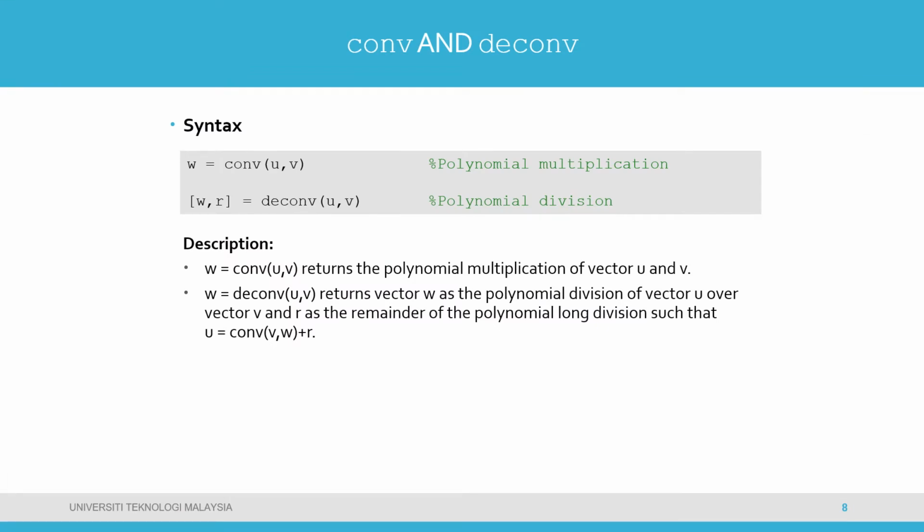Okay, as I mentioned before, you can multiply or divide polynomials. For multiplication, you use conv. If you want to divide two polynomials, you use deconv.